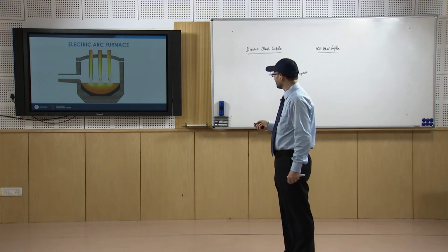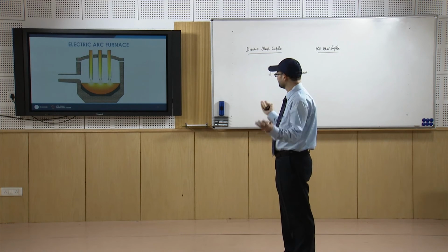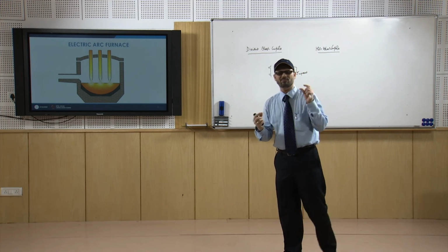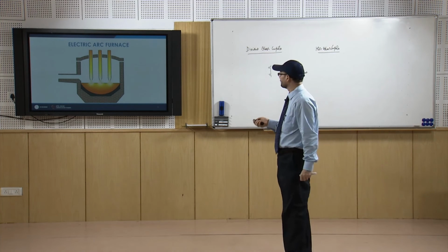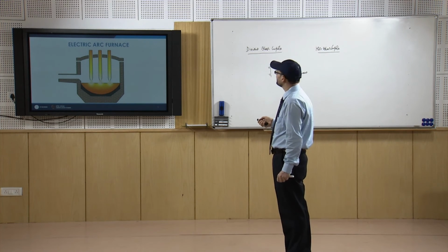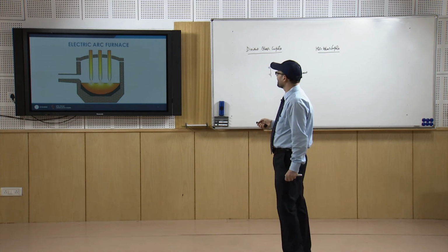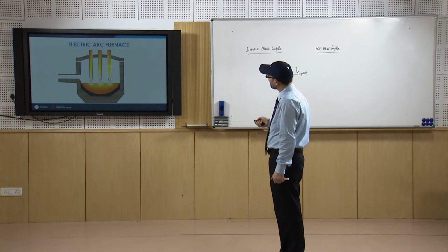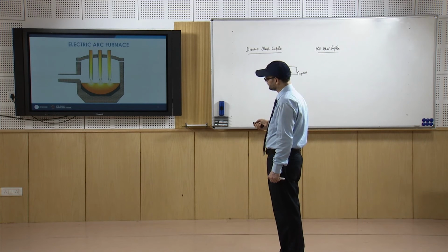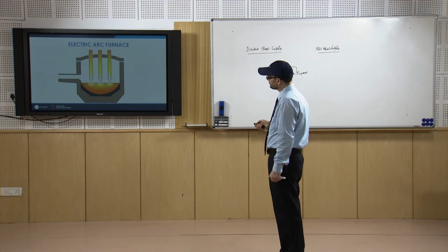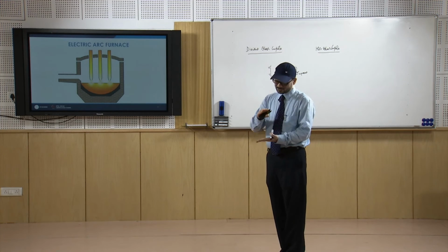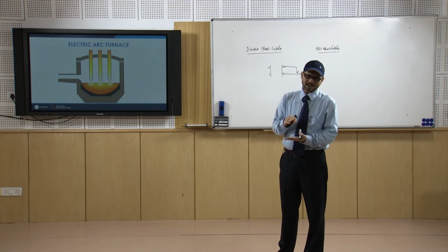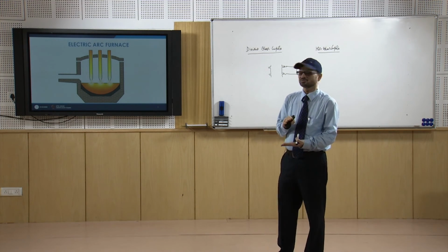These are the furnace linings; you have the steel shell of large thickness, and then you have lining materials, and then these are the electrodes, which may be cooled. Once the electrodes come lower down, at one point of time the spark is generated. When they touch, and then a distance is maintained, the spark is generated.